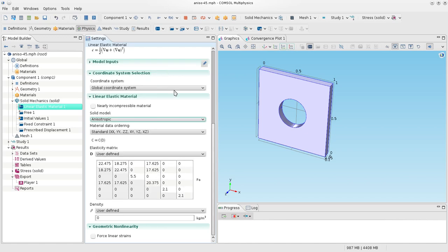So I'll pick the choice of anisotropy, and as soon as I do that, I will have to enter the compliance matrix in its full glory, in 6x6 form. Here what I'm entering is not compliance but the inverse of that, the stiffness, okay, just for the reason that this is what the program requires. But in any case the compliance and stiffness, they show similar features. In particular, you see here there is a 3x3 portion which has to do with normal coupling. When I say coupling, normal, it couples normal strains to normal stresses, because this is stiffness, not compliance.